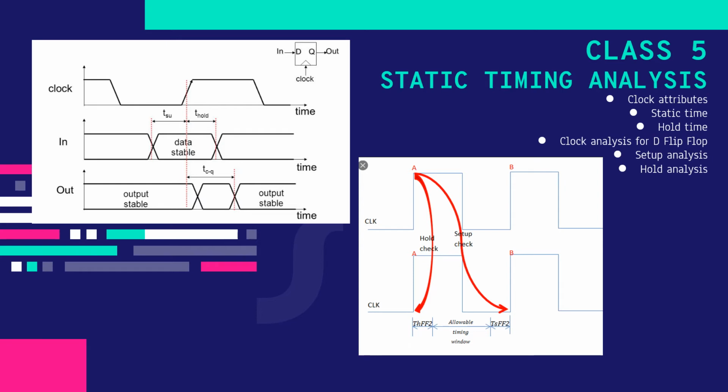We then learned about hold analysis, where we have two things to consider. One is your minimum delay along the data path and your maximum delay along the clock path. If the difference between the data path and the clock path is negative, then there is a timing violation. In hold analysis, to find the delay in a data path, you have to consider only the minimum times.